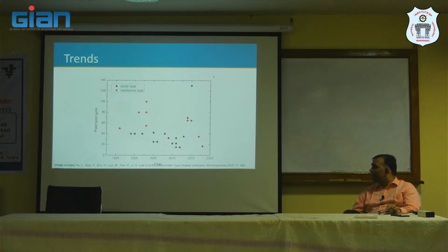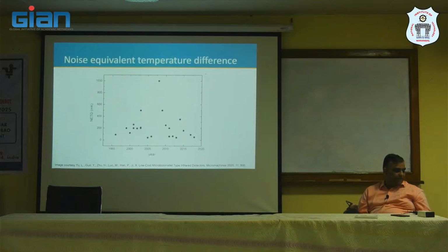Little wonder diode based sensors, their size is reducing because you can make transistor processes in smaller and smaller geometry. But the other thing worth checking is, what was the size of the diode sensor which we took while designing the camera pixel? 3 micrometer by 3 micrometer. These are still significantly bigger than our camera pixel. We are looking at 20 micron, 60 micron or that kind of sizes. So, while we can make an array, the individual pixel is still comparatively larger, which means the number of pixels which we will have is still fairly small.